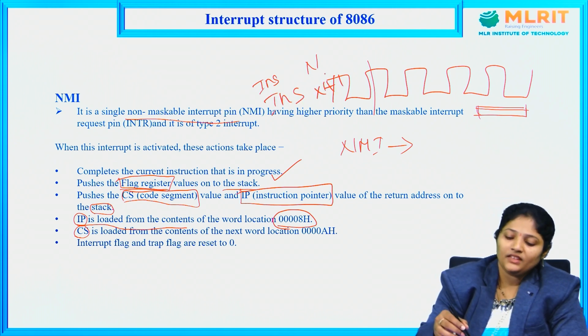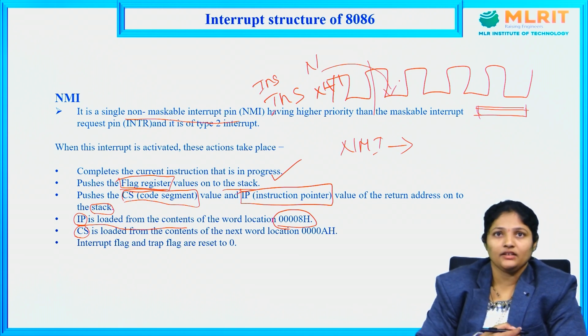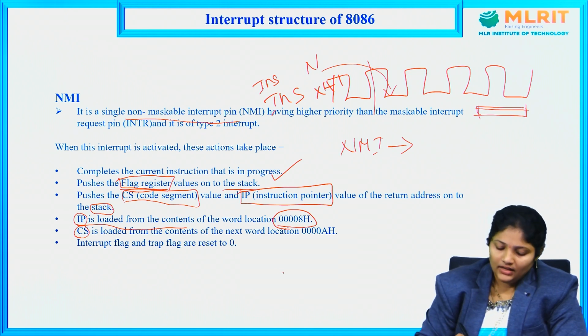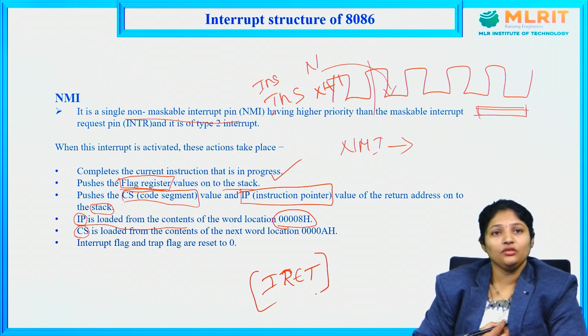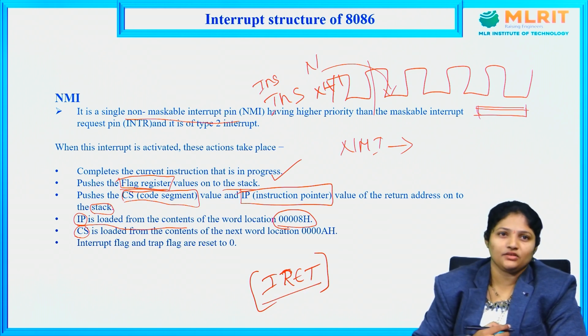So it will jump to that particular interrupt location and execute the interrupt until it fetches the IRET instruction. Every interrupt program will end with this IRET instruction.